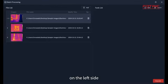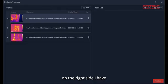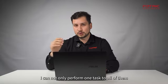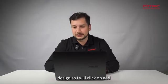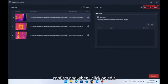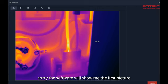On the left side, the software will show me all the pictures that I have selected and that I will batch process together. On the right side, I have the number of tasks that I can perform. This means that I can not only perform one task to all of them, but a series of tasks in the specific order that I design. So I will click on Add. I will go to Markers with the icon for ROIs, Confirm, and when I click on Edit, the software will show me the first picture.